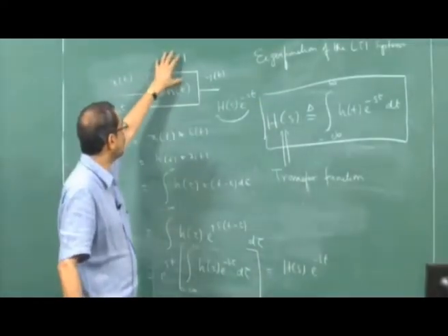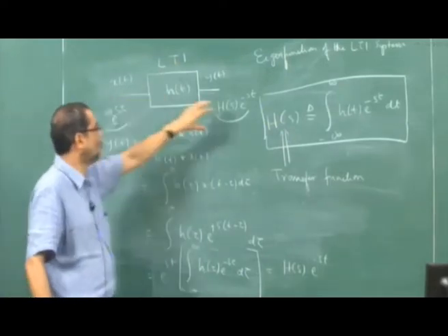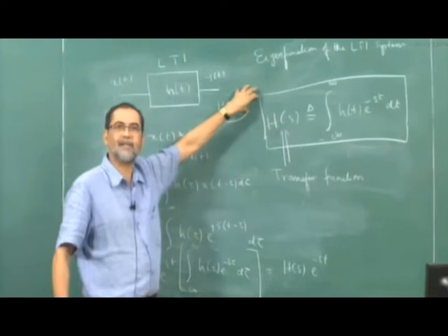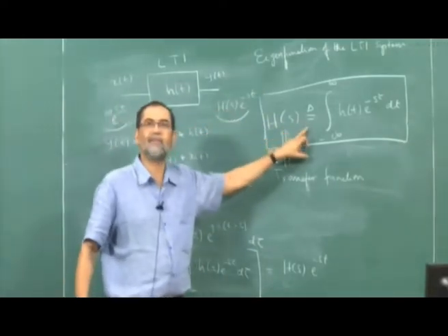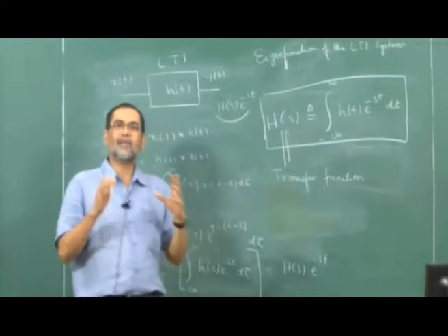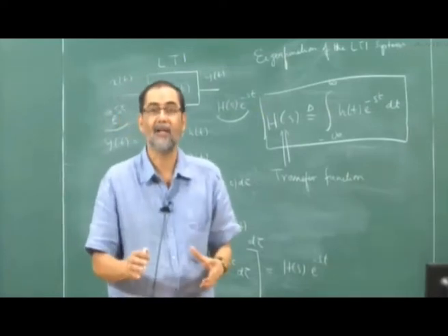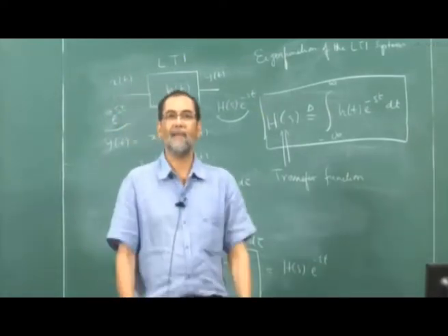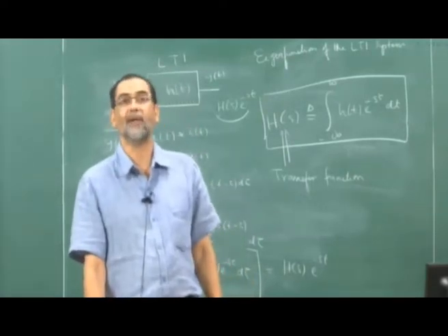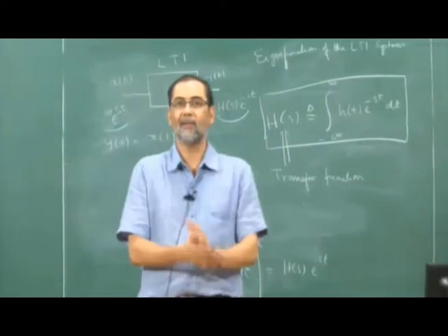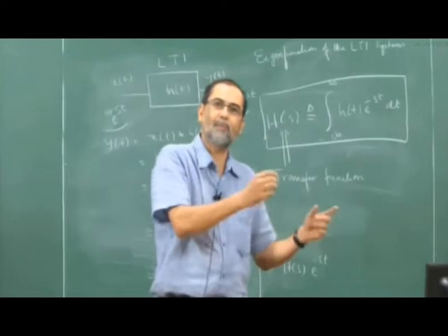An LTI system, for an input e raised to minus st, gives an output with the same frequency, e raised to minus st, with some scaling factor H of s, called the transfer function, defined by this integral. So this idea that linear time invariant systems preserve the frequency leads to the study of linear systems in the frequency domain. That is what I am going to do next. That is the motivation for switching to the frequency domain. I'll ask questions, so please ask me questions.